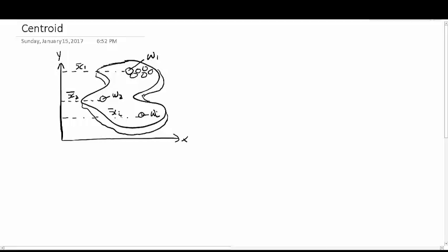Well, we know that there's going to be a centroid on this piece, so maybe it's right here. And this has some total resultant weight. Here, I'll draw it down further. So this is some total weight. And the distance from this centroidal point to the y-axis we'll call capital X bar. That's the overall X bar, the center X location for this plate.